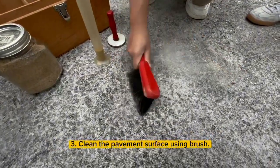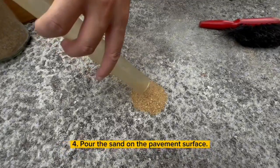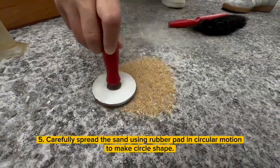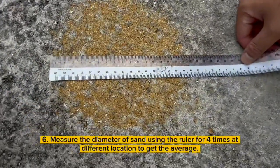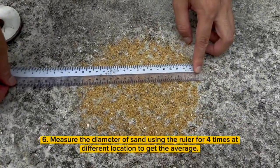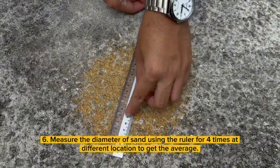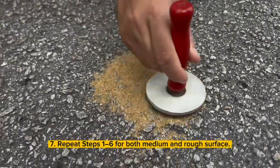Clean the pavement surface using a brush. Pour the sand on the pavement surface and carefully spread the sand using a rubber pad in circular motion to make a circle shape. Measure the diameter of the sand using the ruler 4 times at different locations to get the average. Repeat for both medium and rough road surfaces.